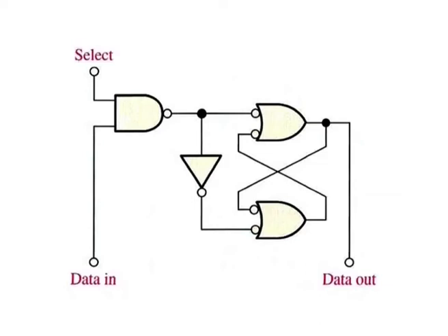All static RAMs are characterized by latch memory cells. As long as DC power is applied to a static memory cell, it can retain a 1 or 0 state indefinitely. If power is removed, the stored data bit is lost. Figure shows a basic SRAM latch memory cell.